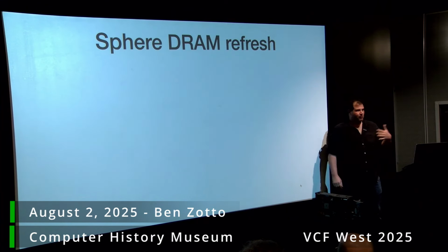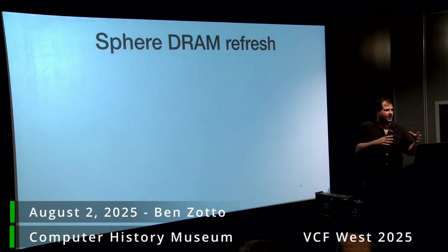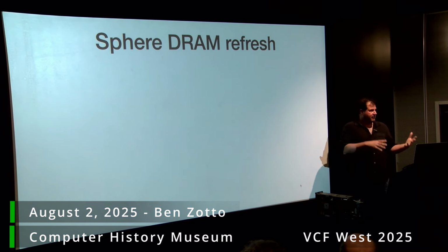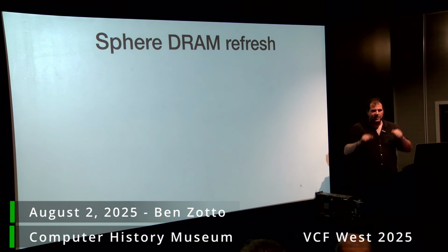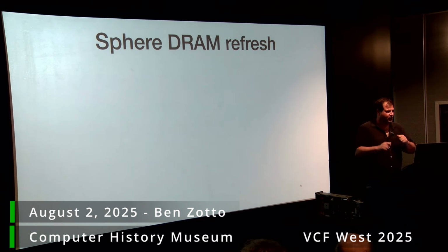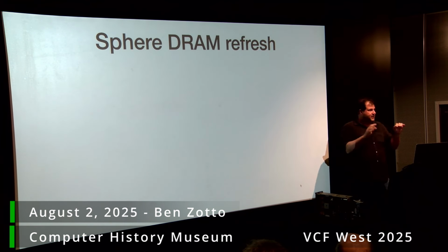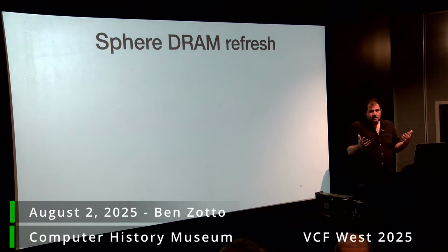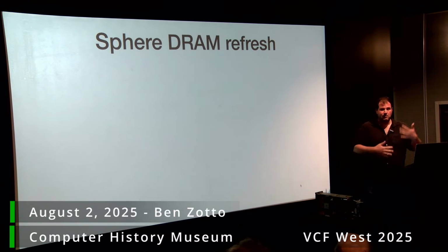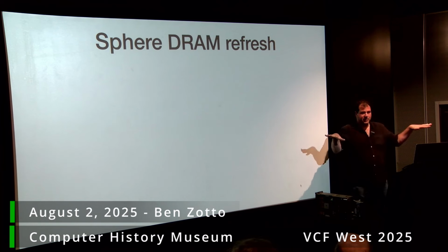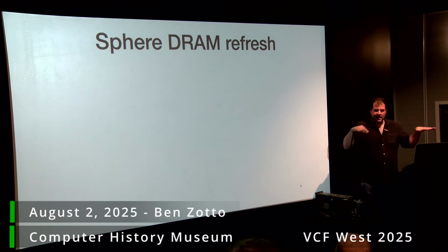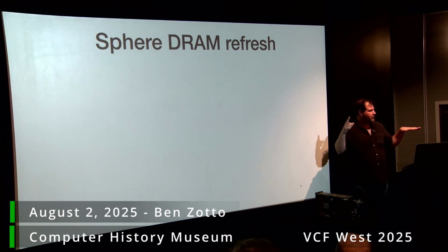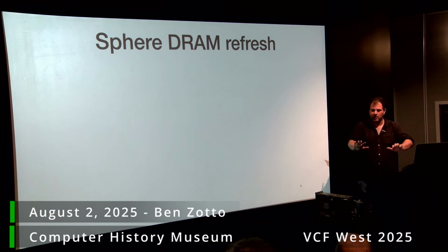The Sphere uses dynamic RAM, which was a relatively new innovation. They were a very early microcomputer to use it. DRAM needs to be refreshed. Refreshed just means you have to tickle it in certain ways to keep the capacitor bit charged. The way Sphere chose to do it, though there are cleverer ways in some systems, was to set a 2 millisecond timer, and every 2 milliseconds it freezes the world and halts the computer. It counts up some addresses that do the right RAM refresh, and then it lets the computer go again.